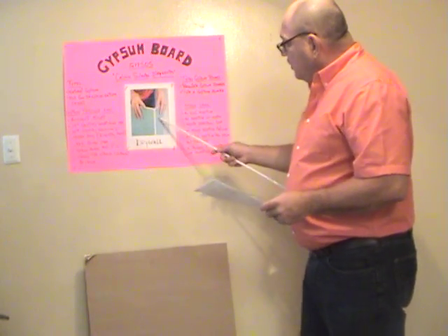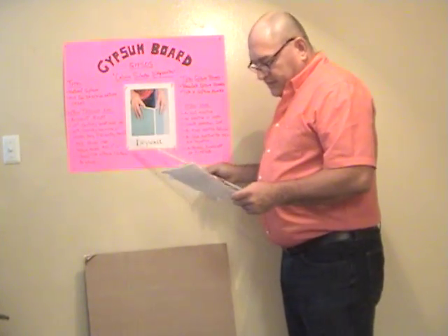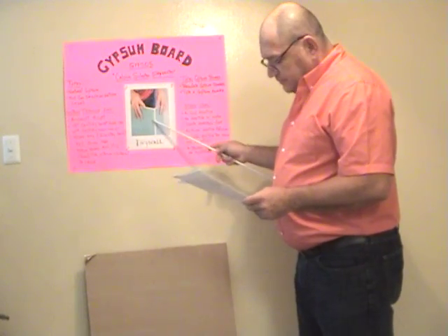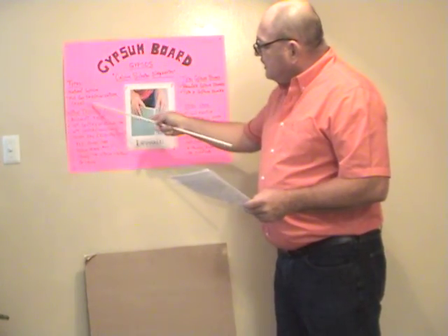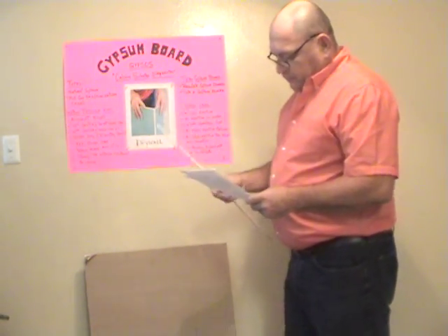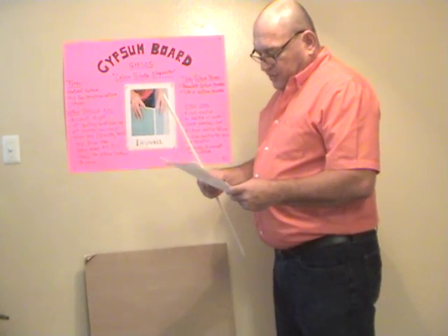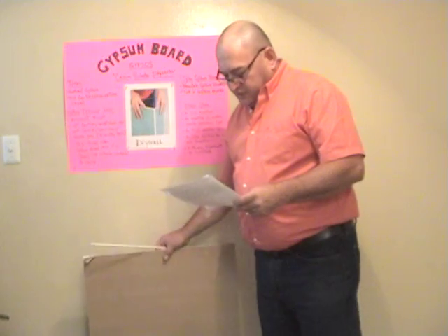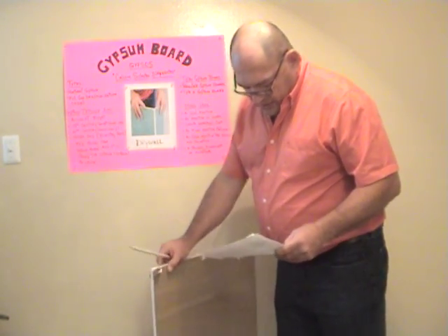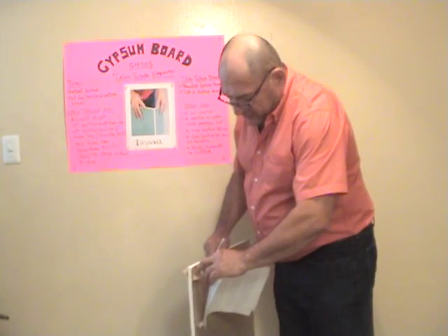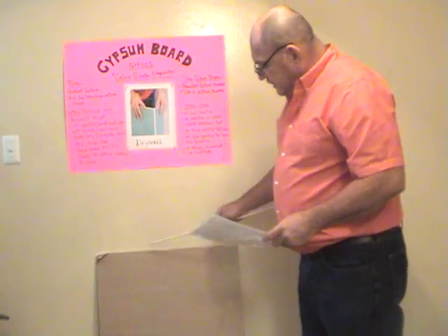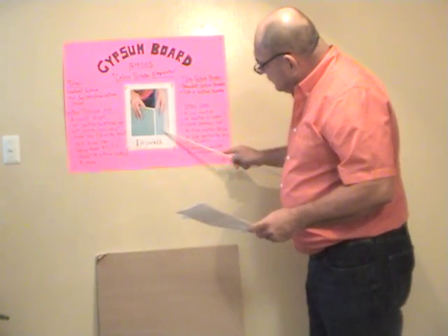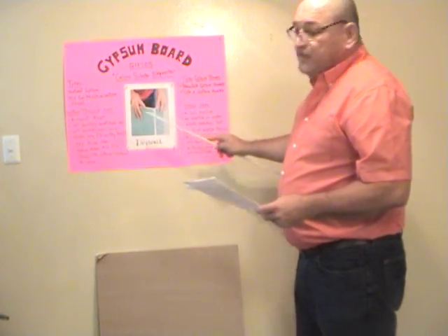Making gypsum board. How do they make the gypsum board? They produce it from calcined gypsum, like natural gypsum or FGD gypsum, and with water and additives form a slurry which is fed between continuous layers of paper on a board machine. The paper becomes chemically and mechanically bound to the core. The board is cut, and the lengths are conveyed to the dryers to remove any free moisture.